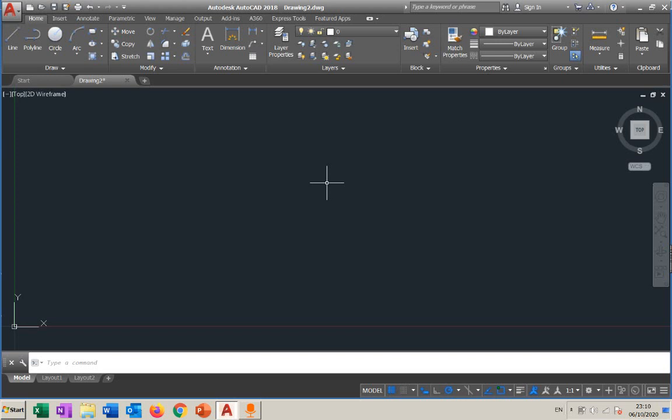So we will teach you how many methods, for example, are available to draw a line or a circle. You know the methods, but you don't need to memorize them. Why? Because anything that we do, for example, I'm going to choose the circle here. I don't need to memorize what the first step was. I can simply read here: circle is active, and the last part says specify first point on circle.